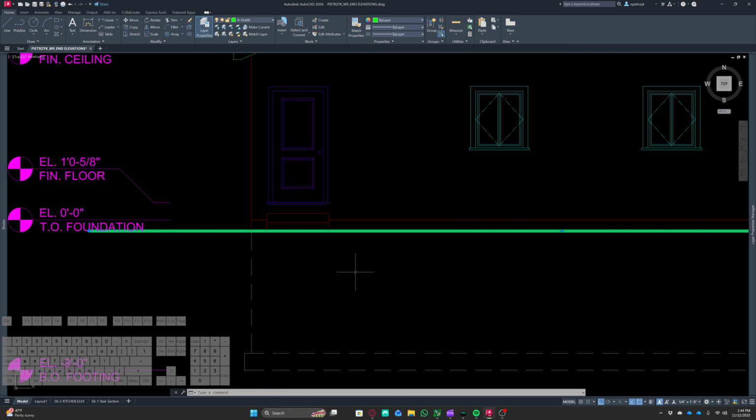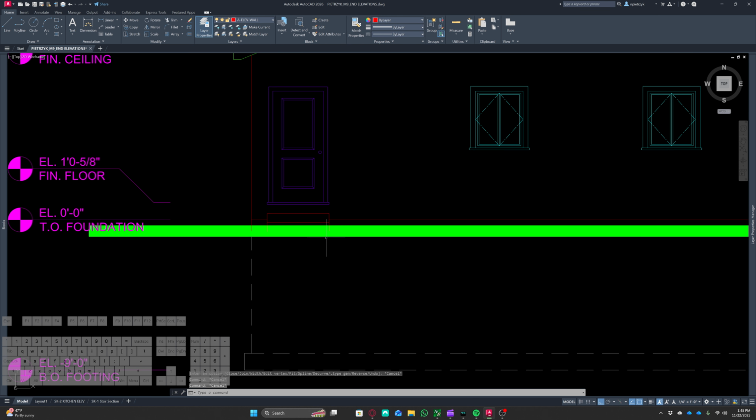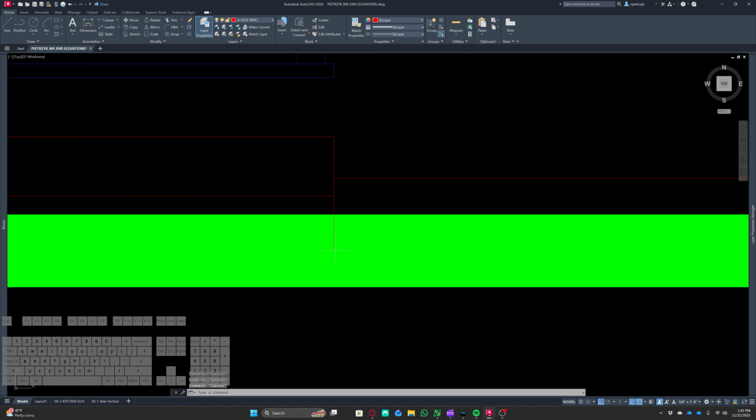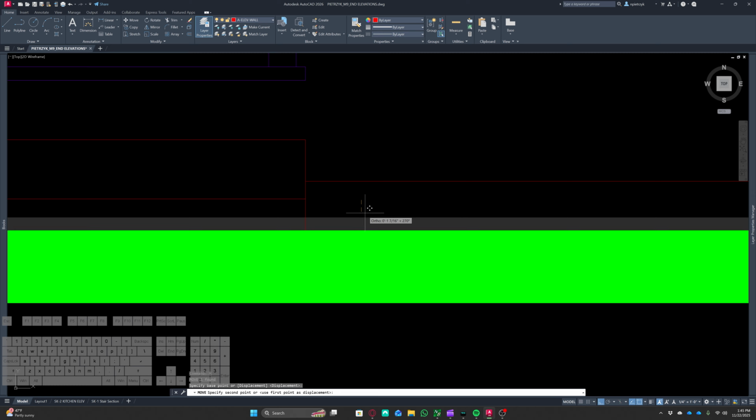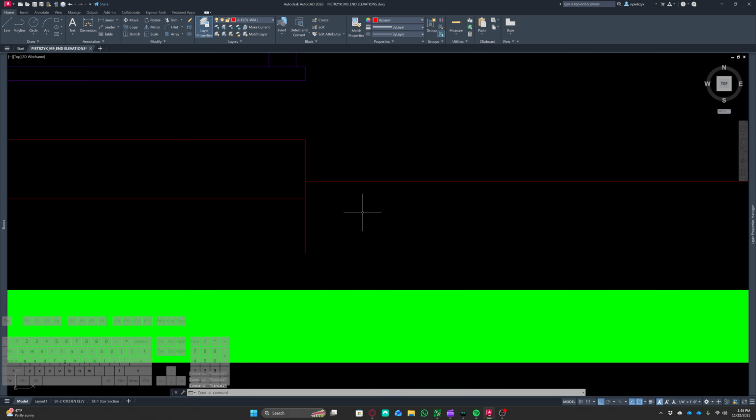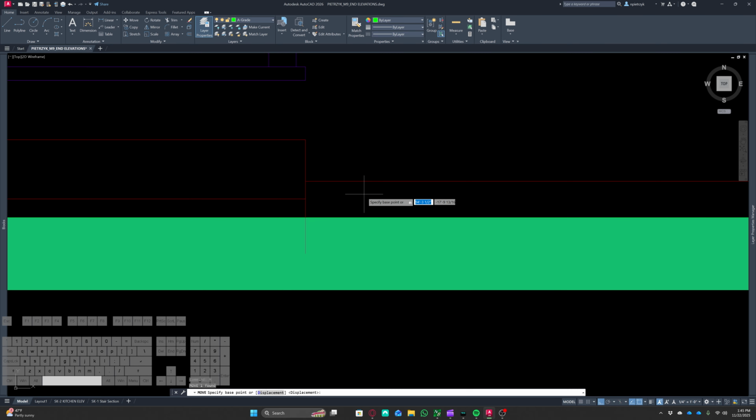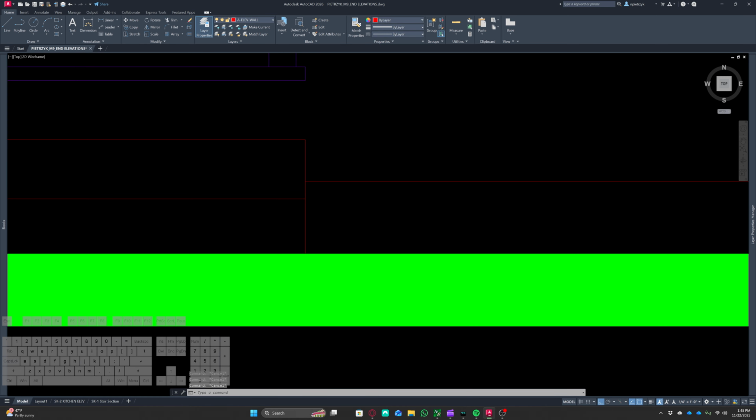And all I'm going to do is go to P-Edit. I'm going to select width, and change it to be 8 inches. Now, you may notice this looks kind of weird, but these lines go to the center, which is accurate. I'm going to perform a move command and move it down 8. Sorry, not 8. I'm going to move it down 4 inches, that's half of 8.